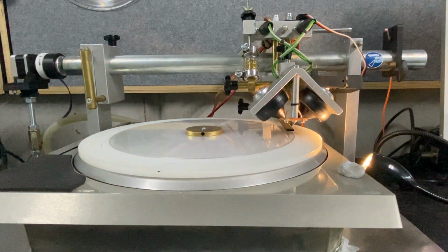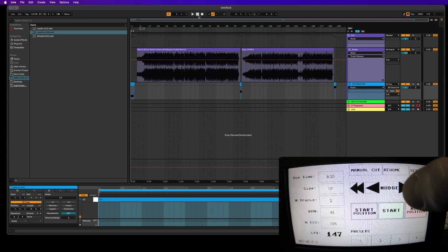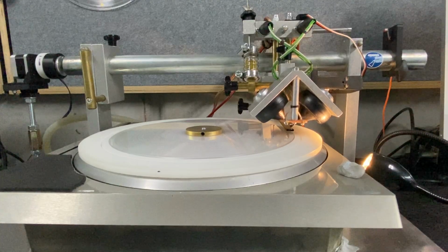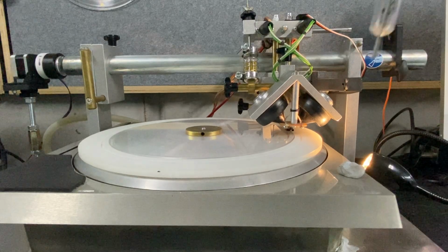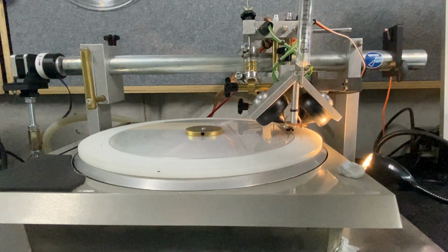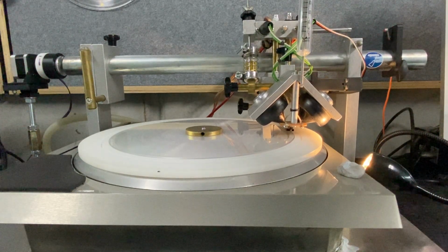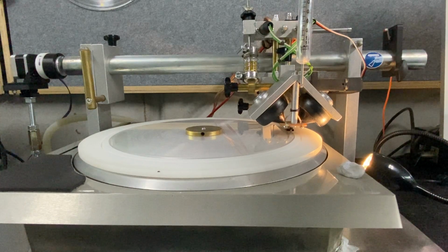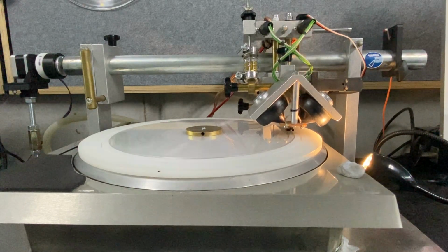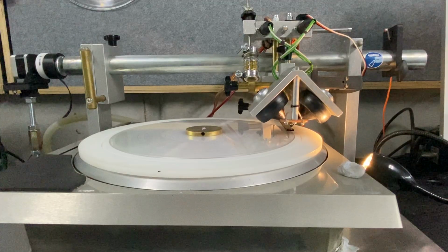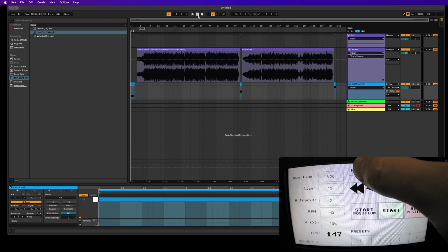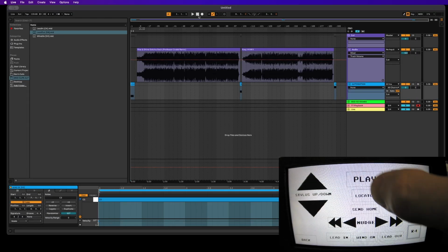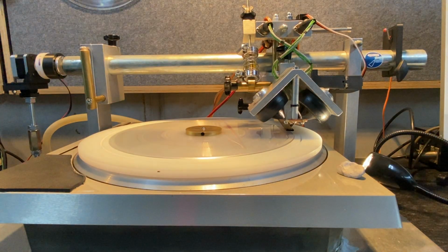I'm also just going to check the weight quickly, and you can do this by going to the manual cut page, stylus head down, and then just checking the weight there. Happy with that, so I'll move the stylus head up. Also, when you exit the manual cut page, the head will automatically go up as well. I'm just going to turn on the light here as well.